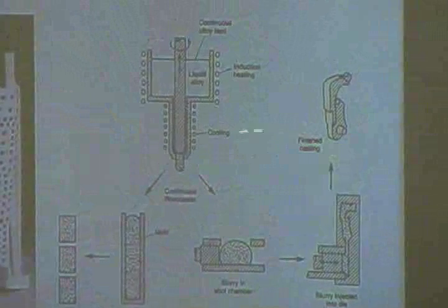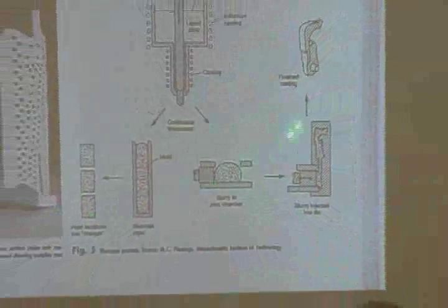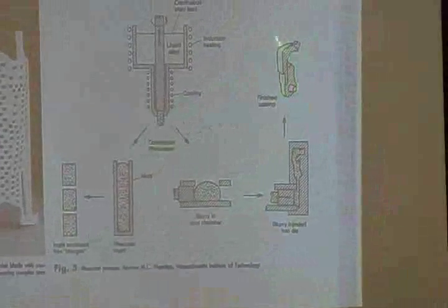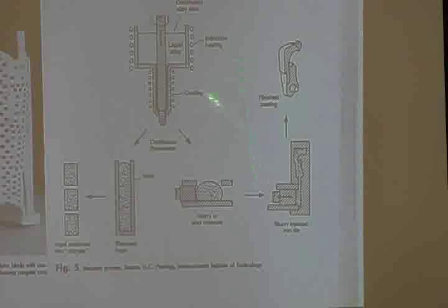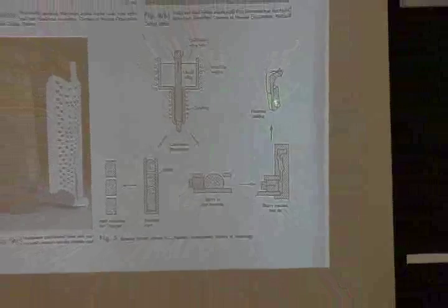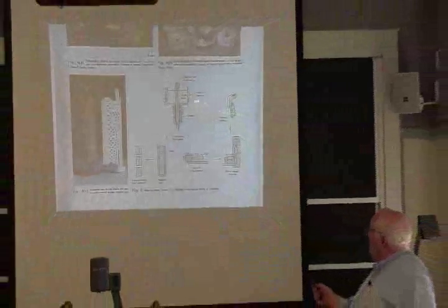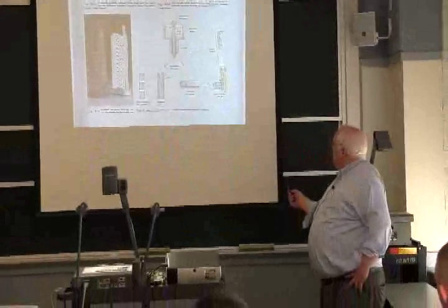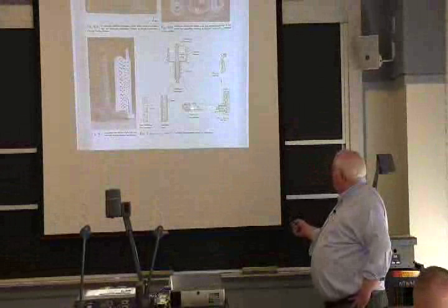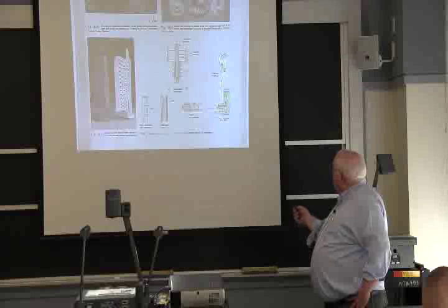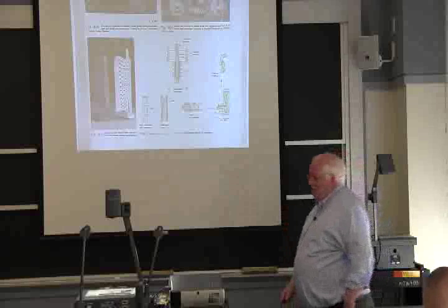These are actually some of Professor Fleming's drawings. They're in a book now, but I recognize this. This is the firing pin for a U.S. Army, I think M16. Okay, the Army gave them millions of dollars back in the 1970s to see if they could injection mold a semi-solid steel. Okay, and this is actually injection molding. You're pressing the semi-solid material into the cavity, and the cavity actually is that firing pin.